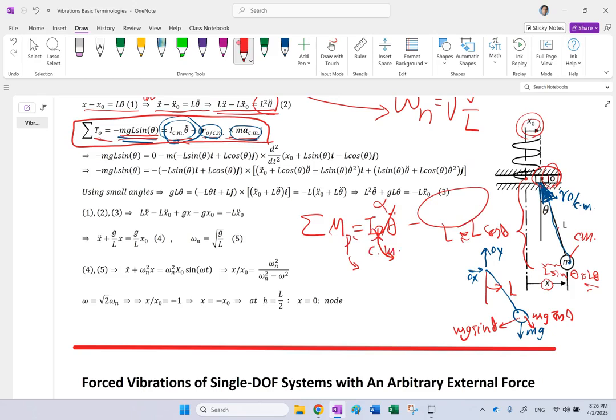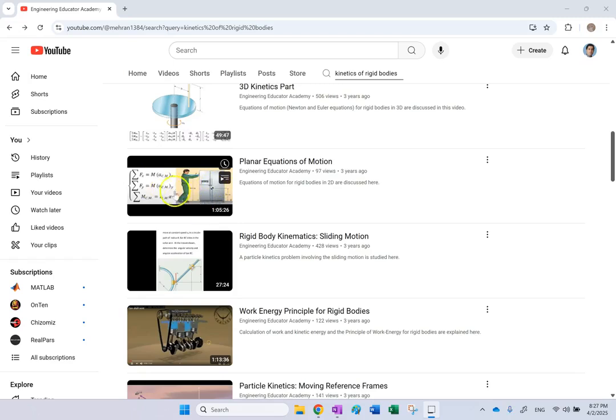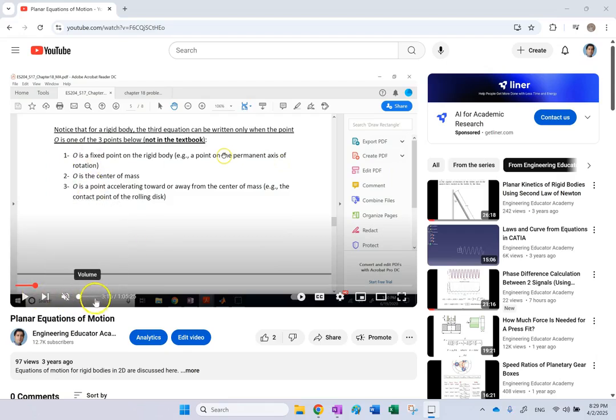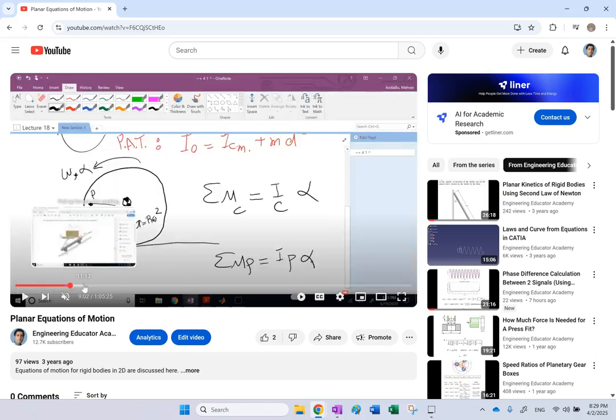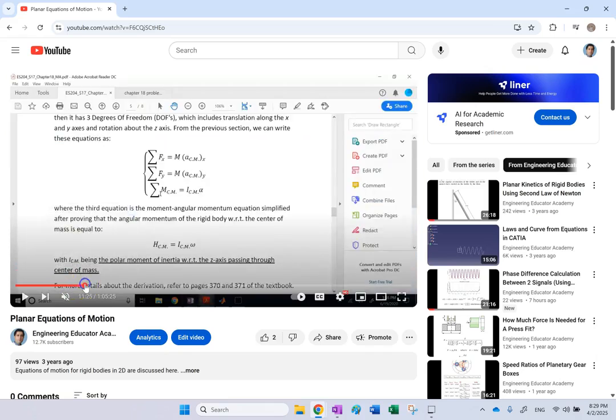Okay, so if you want to know that, there is a video on my channel where I talked about kinetics of rigid bodies in 2D. That's this video here. It's called Planar Equations of Motion. If you go to time 3:15:16 in this video, here is the part where I'm explaining that the equation can only be valid for a permanent fixed point or center of mass, or if the point is accelerating toward or away from the center of mass. If the point is an arbitrary point, then that relation is not going to work.